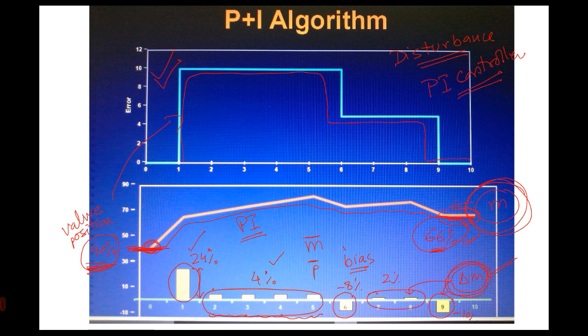Next we have a change in the error, and the proportional contributed around -8. Next we have a valve movement of 2% for 2 steps, and finally a contribution by the proportional, and the system is stabilized here.